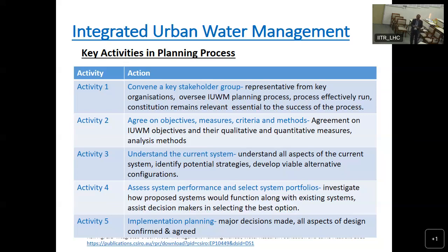So when we're looking at the overall environmental impact, we are considering not only the energy that is required in providing services, running the motors, running the pumping plants, running the boosters, but also the energy required in laying and manufacturing those pipe network systems. It is not only the pipe network, it can be the motors, it can be the parts of the treatment plant.